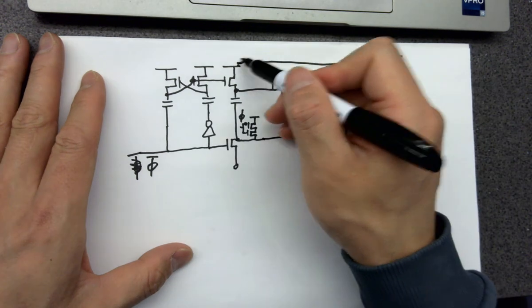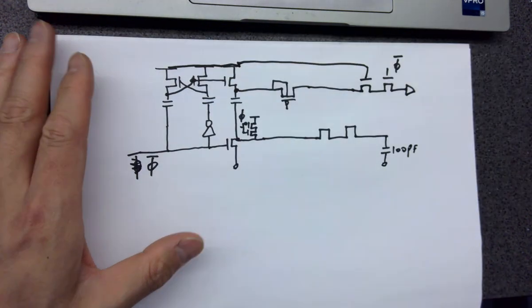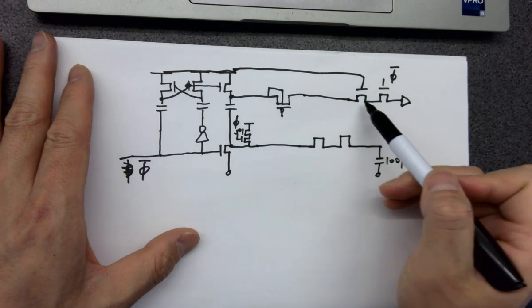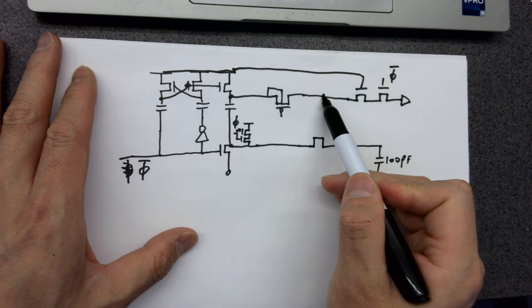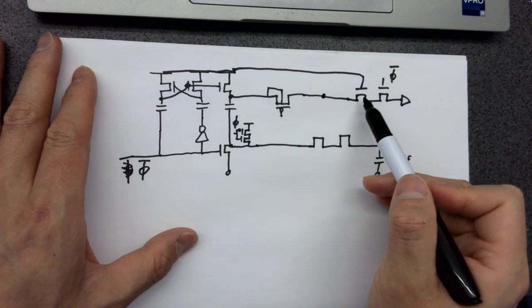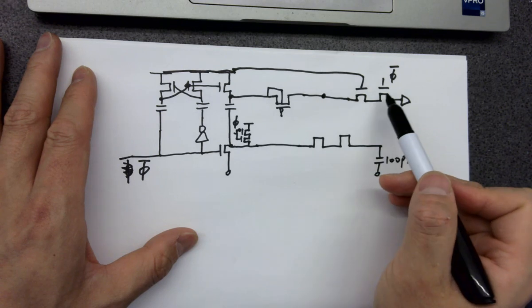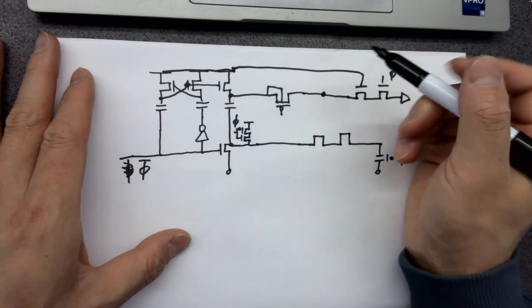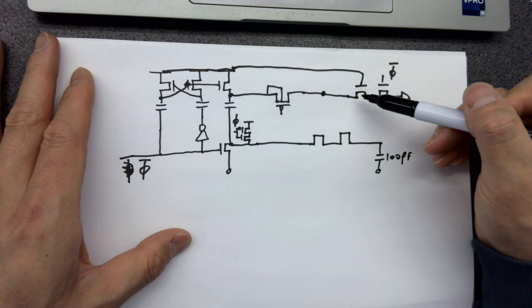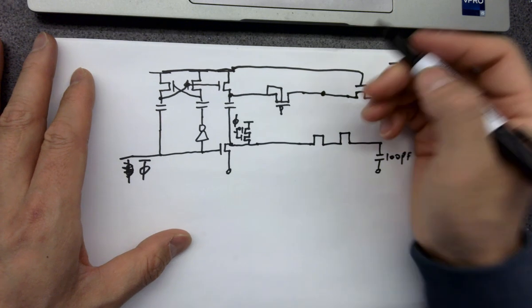Okay, and this is always on. This guy's always on. The reason for that is this is trying to protect, because you've got relatively higher voltage over here, higher than VDD. So this one is trying to protect this transistor. So making this a little bit white, but it's always on, right? And